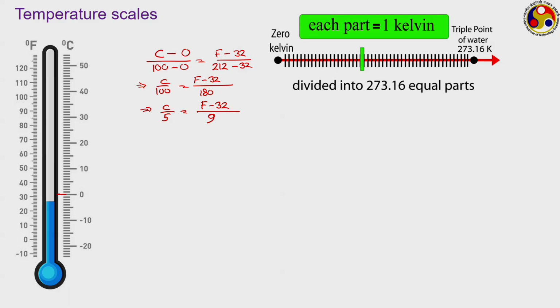Now, these two are relative temperature scales because this choice of steam point and ice point has been decided by us. If we are looking for absolute measurement we have to go to the absolute scale, just like the Kelvin scale, where absolute 0 is marked as 0 Kelvin and the triple point of water, generally taken as standard, is given the value of 273.16 Kelvin. The division between absolute 0 and the triple point is divided into 273.16 equal parts, with each part signifying 1 Kelvin. So, Fahrenheit and Celsius scales are relative scales of measurement, whereas this is an absolute scale of measurement.